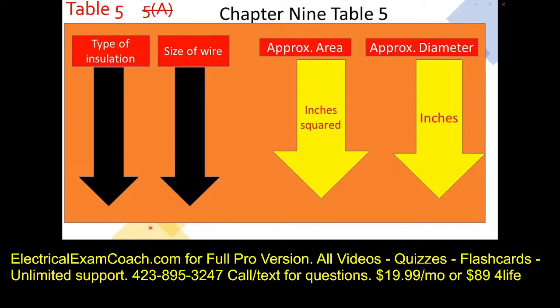So we're going to head here and start on the left-hand side and find our type of insulation. Then we're going to cross over and find our wire size. Then we have to be careful here. We want to make sure that we're in the approximate area and that we're in the inches squared. We're not dealing with diameter for pipe fill, although there may be a time that you have a question that asks you for the